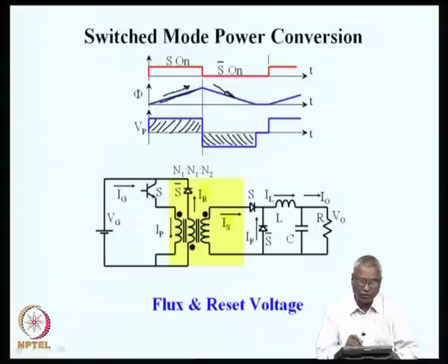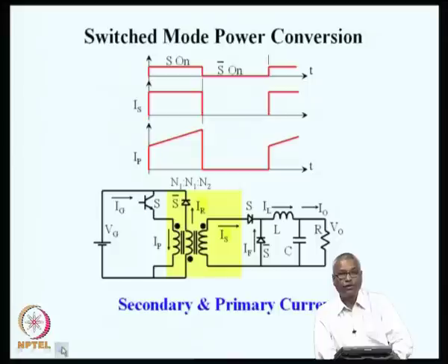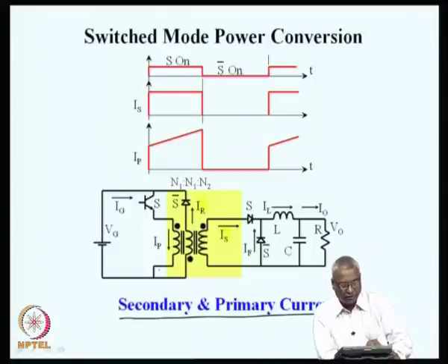Because of the diode in the circuit, the current does not reverse in the winding and the flux also does not reverse. That is the process of reset.